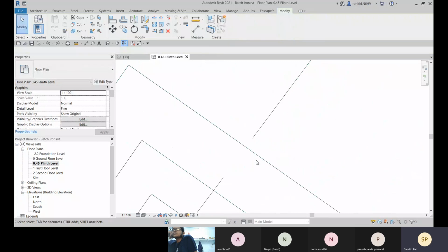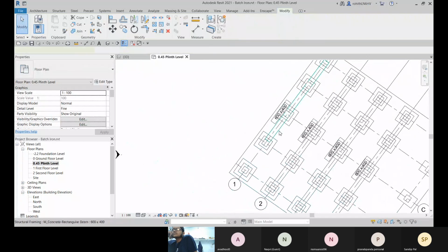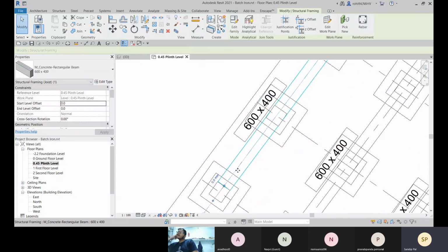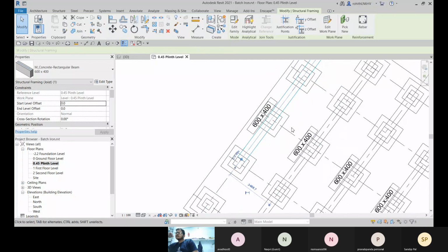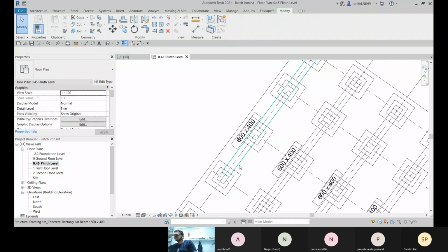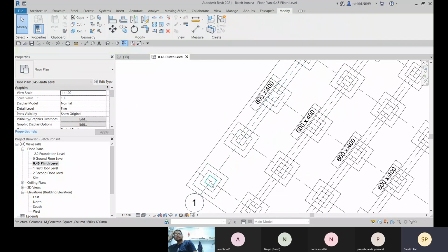Yes, sir. We will fix it. Fine. And if you make it a continuous beam, what will happen? It will clash with your column, so that is not needed. We will not have a clash within our model. Otherwise, we have to fix it again while checking the clashes in Navisworks or in BIM 360. We have to delete or remodel it. So it is better to always go with a clash-free model while you are modeling it.